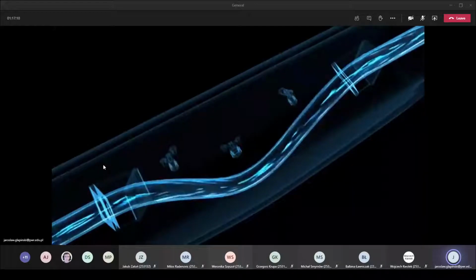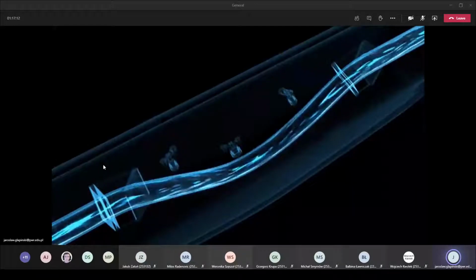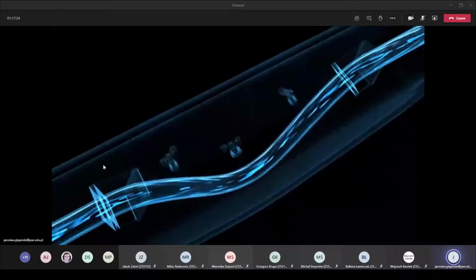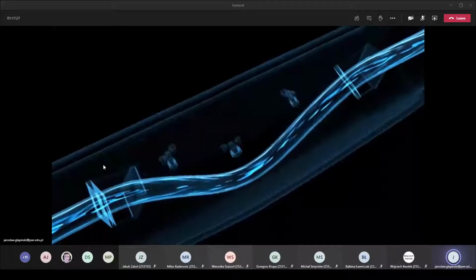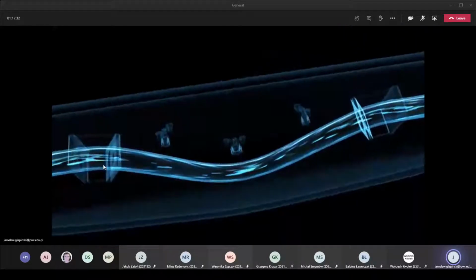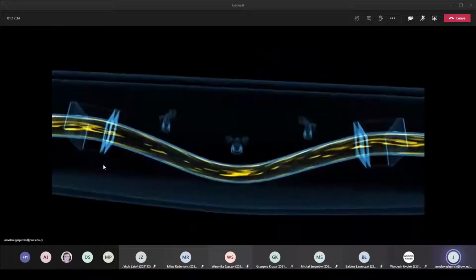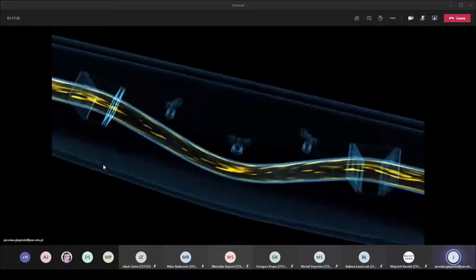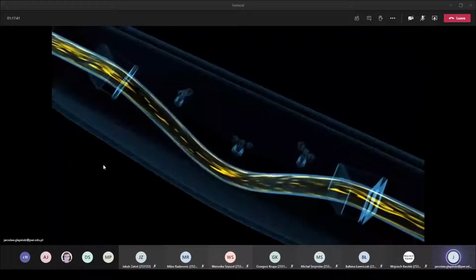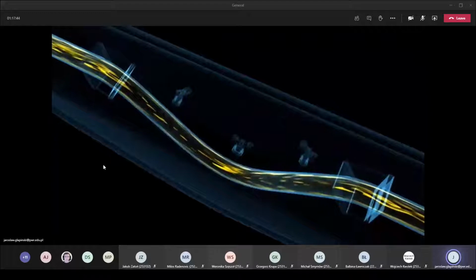It can also be used to simultaneously determine the density of the flowing fluid. To do so, the sensors also register the oscillating frequency. In other words, how often the measuring tube moves back and forth in 1 second. From the animation, it's clear that a tube filled with water oscillates more frequently than a tube filled with honey, for example, which has a far higher density. Thus, the oscillating frequency is a direct measure of the fluid's density.